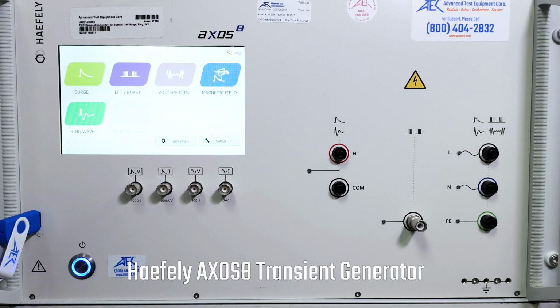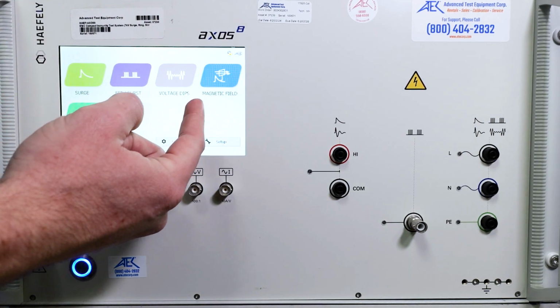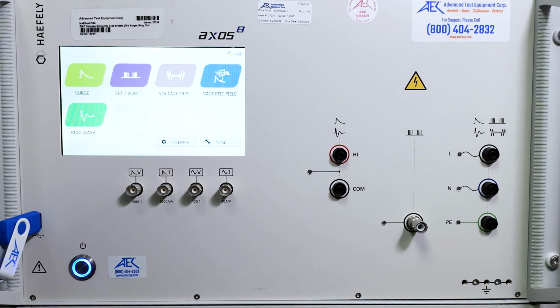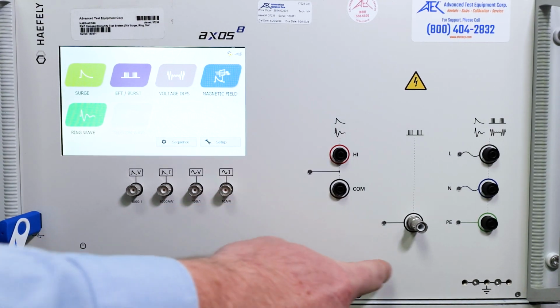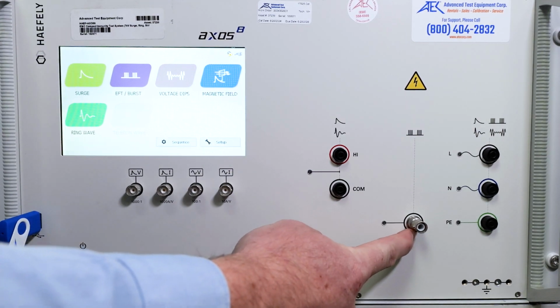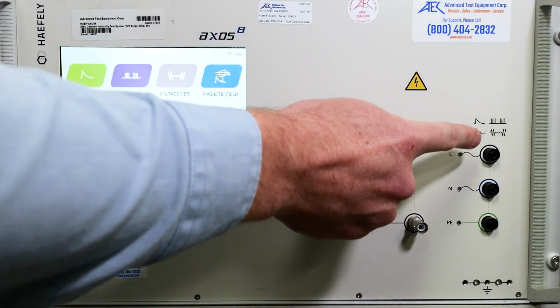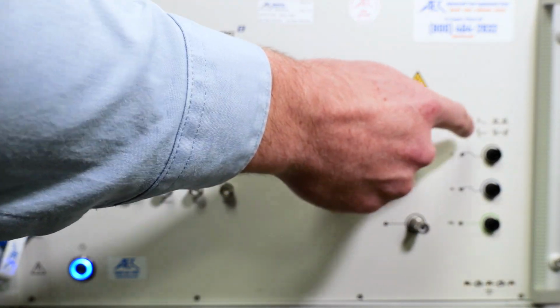Here we are with the AXOS 8 transient generator that is capable of doing surge, EFT, voltage dips, magnetic field, ring wave, and telecom wave with certain accessories on the front panel. You have your surge and ring wave output from here, direct, your EFT direct output, and then your built-in single-phase 16 amp coupling network, which will do all of these waveforms, the surge, EFT, ring wave, and the dips and